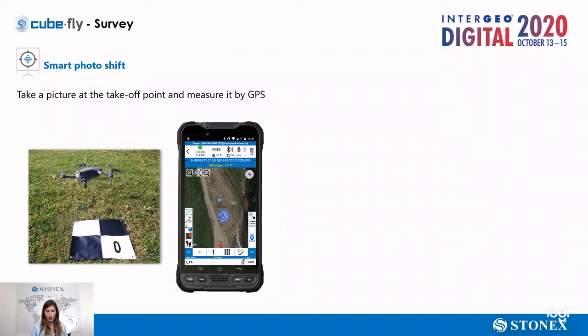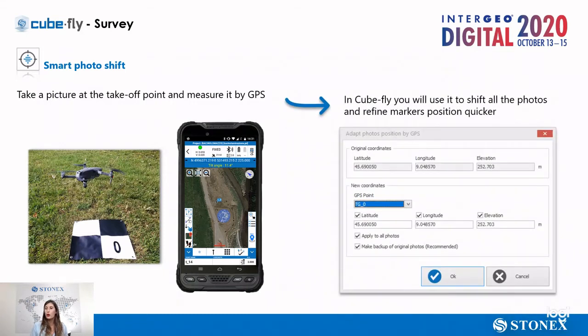So from the picture at the takeoff, you have some EXIF coordinates inside the picture. You have the coordinates that you measure by a GPS, which of course is more precise. And in the software, when you post-process all your data, you will use this takeoff photo to shift all the other photos.